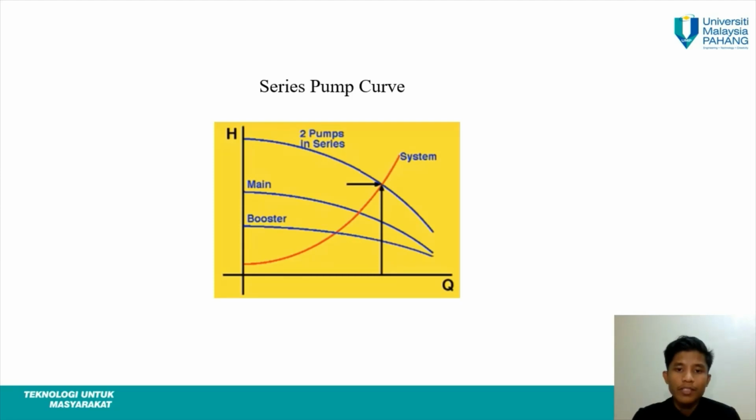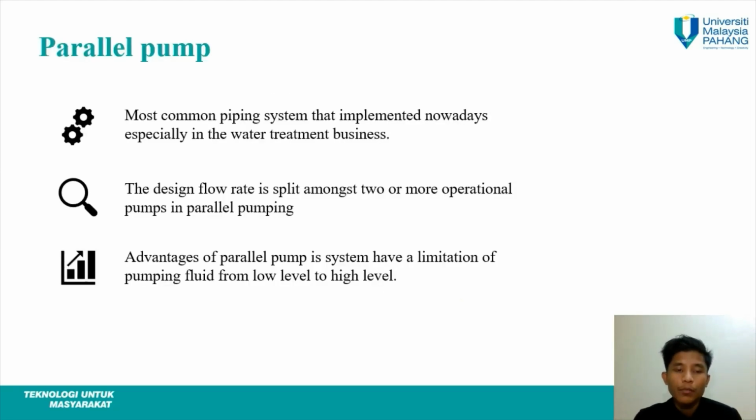This figure shows the series pump curve. For the experiment, if we use two similar pumps, they will operate at the same flow rate but deliver a different level of head. Next, we continue with the parallel pump.